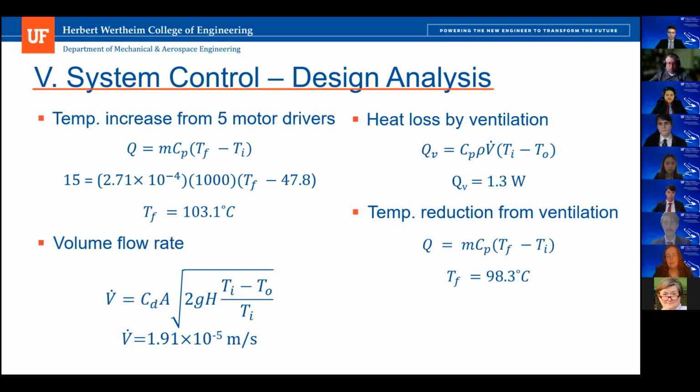It's also important to consider because this value is lower than the glass transition temperature of PMMA, which is 125 degrees, because the plastic casing of the control box is made from that material. And it's important to stay below the glass transition temperature because if the temperature were to go above that value, the polymer would transition to a softer material and change its molecular structure. Next, we'll discuss the key features of our design.